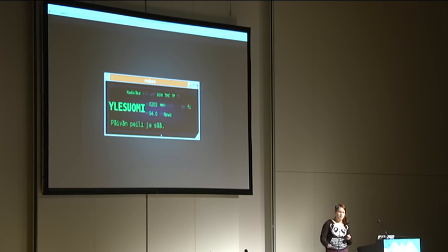It turned out that the stereo decoder in my radio had somehow stopped filtering the stereo signal, which is near the RDS signal. So this is actually being decoded from the audio, from the line out of my radio. Nothing else was involved with this. But then, it's a bit noisy. It's near the 16-bit quantization noise limit of my sound card. So I was thinking of better ways to decode it with less noise.